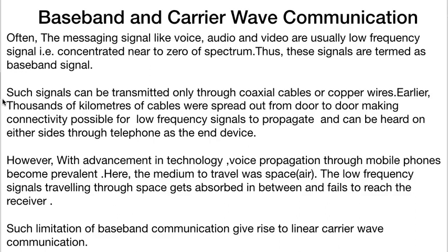Such limitation of baseband communication gave rise to linear carrier wave communication. I hope you have got why there is a need for modulation. Baseband signals lack the energy to be transmitted through the air, so they are modulated on high frequencies so that they can be transmitted easily through air without getting disturbed by channel disturbances and get received at the receiver.